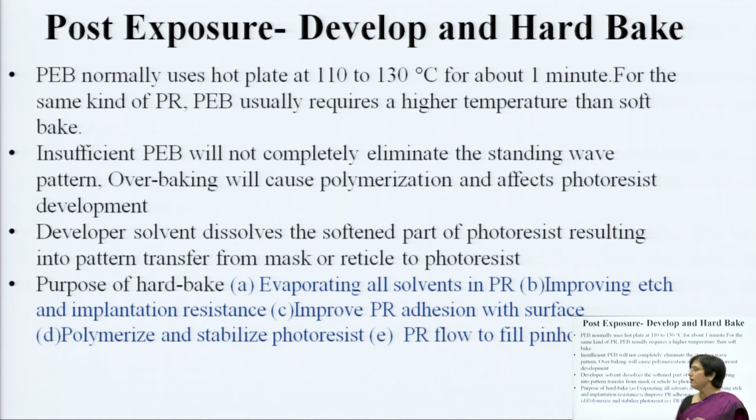Especially, what is the exposure doing? In case of negative photoresist, when you are exposing, the photosensitive material comprises polymers, and these polymer chains become strong. Because of the increase in strength, multiple chains get formed, the molecular structure becomes heavy, and therefore the material or PR becomes strong. Whereas in case of positive photoresist, the resin loosens, or the bonds available in the resin break, and therefore the material gets easily dissolved.